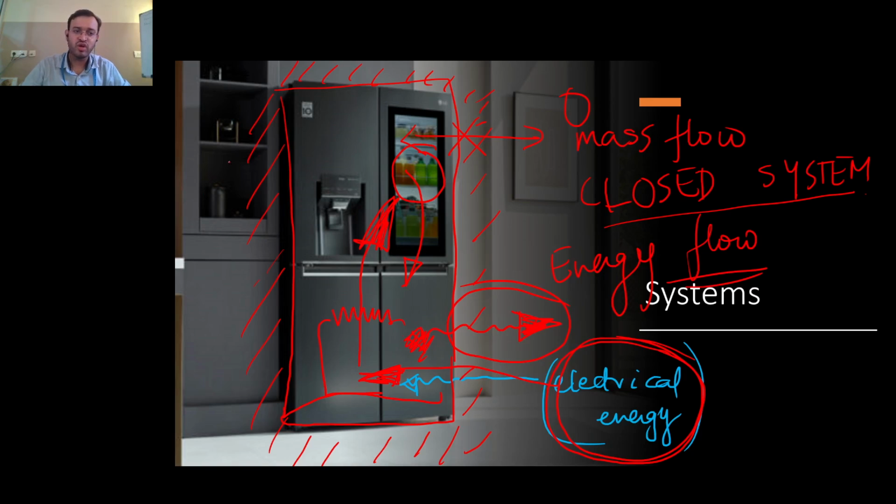It is because you have placed this insulation. So in this case you still have electricity flowing into the system. However, there is no heat flow out of the system or into the system. Do you understand? There is energy flow, in terms of electrical work being done on the system. However, there is no heat flow across the boundary.